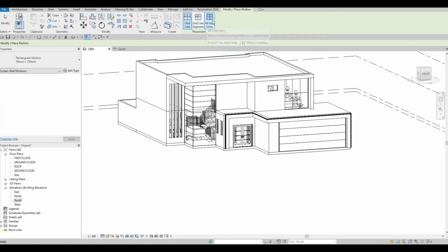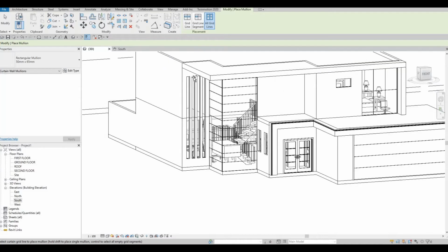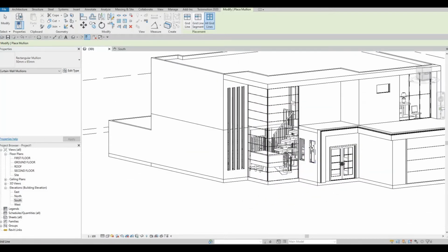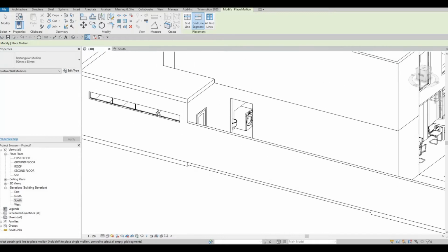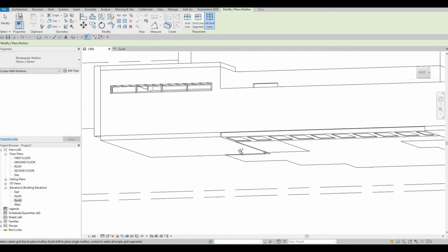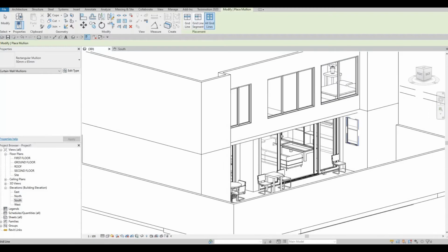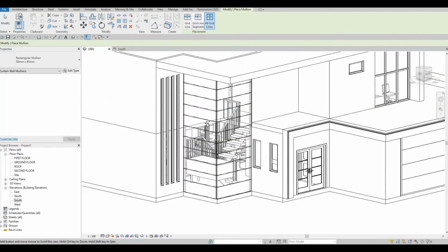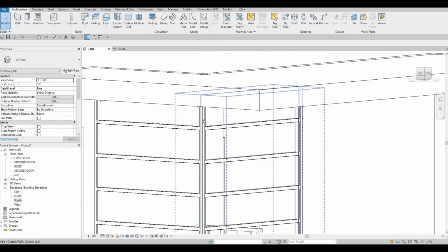And then now click on mullion and then all grid. And then let's change this to 50 by 65. Here I'm going to select this one. I'm going to leave this one at the last. And then I think we did everything. Now let's just add this one on this side and then this side. And then the ones in the middle, we're going to delete.